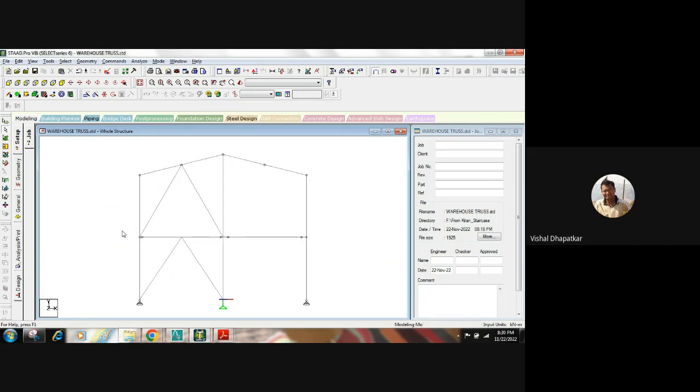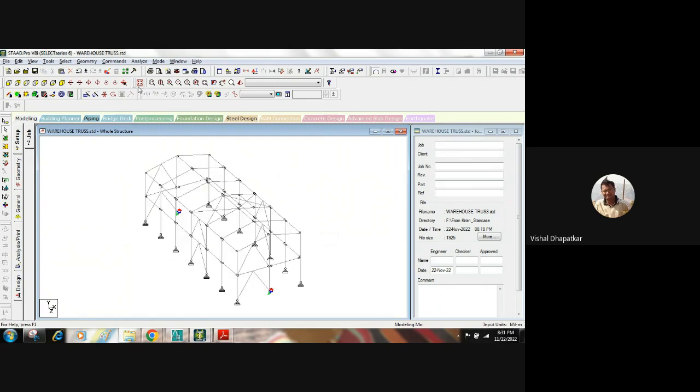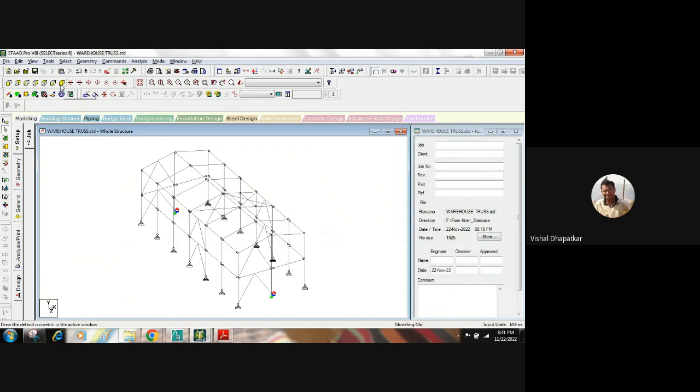It depends on how you can reduce the slenderness of the member. There are many ways, like you can add some beams here, 2 or 3 beams. If this section size is getting much bigger, then you can add another section somewhere here, or if this bracing size is failing in slenderness, then you can add some more members here and we can shorten the bracing. So there are multiple ways. It depends on how you can optimize the structure.